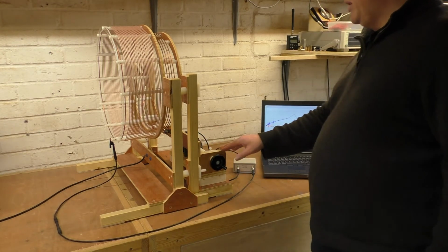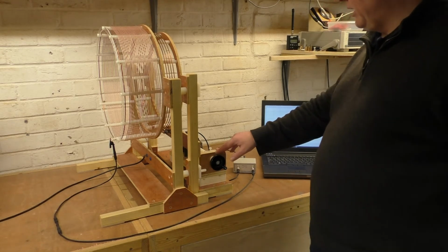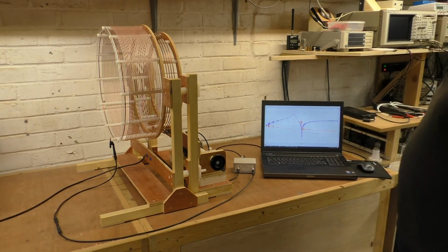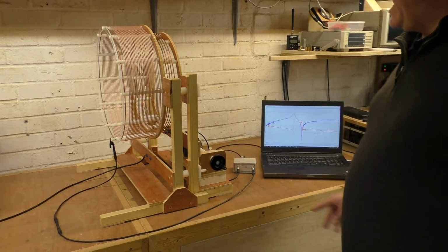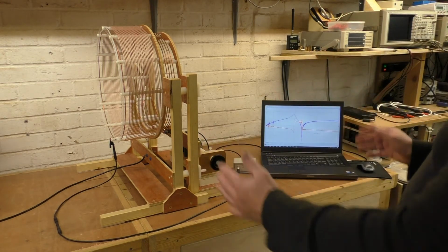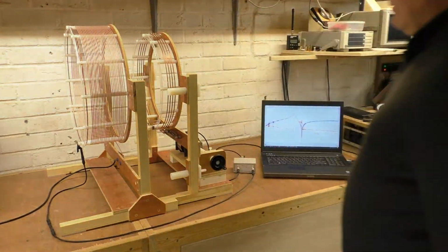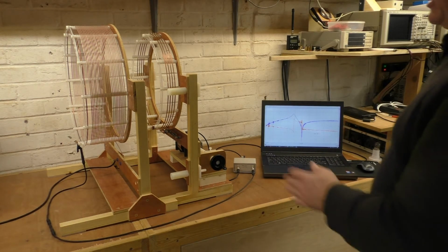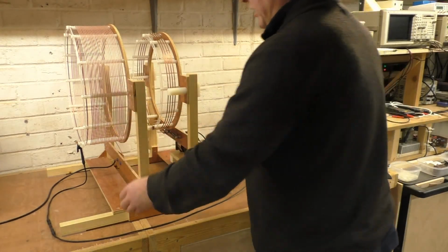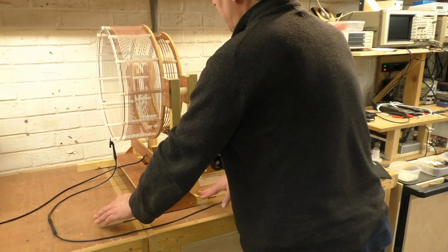That's a normal 1200 picofarad vacuum variable capacitor, 4 kilovolt, that I use for many of the experiments on transference of electric power. Also, because these two coils can be separated, we can change the magnetic coupling coefficient K between them by changing the distance, so the experiment can also be done as a function of distance between the primary and secondary.